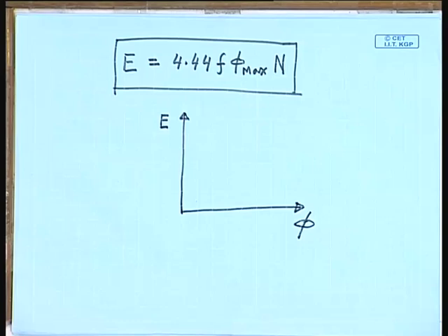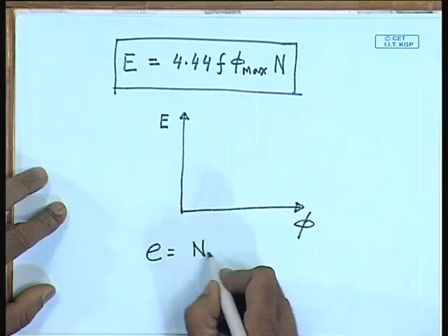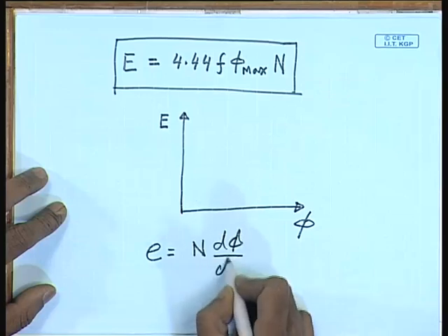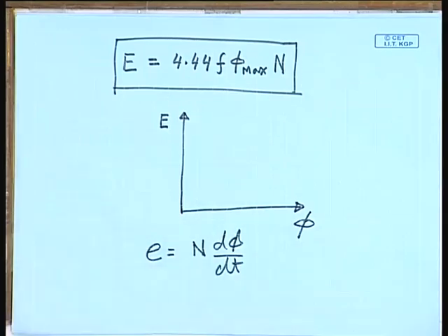The quantity that we have been calling induced voltage is, in fact, called the counter induced voltage by many authors, because here we have got this E by simply saying E equal to N d phi dt, and we have incorporated the last part of Faraday's law, that it opposes the very cause due to which it is produced, by taking its proper polarity. This many authors call the counter induced voltage.